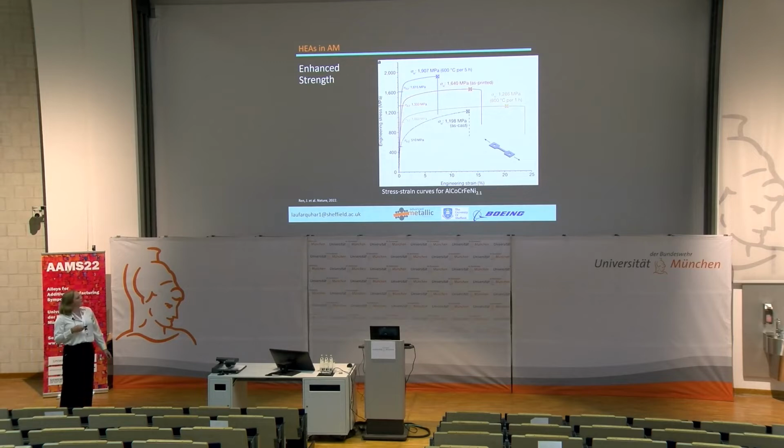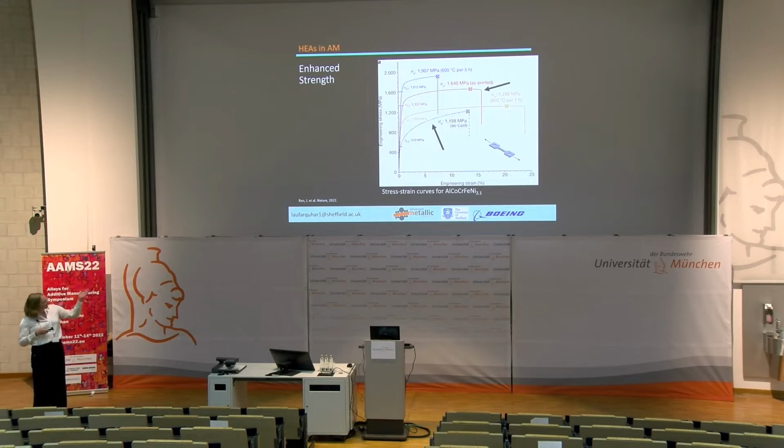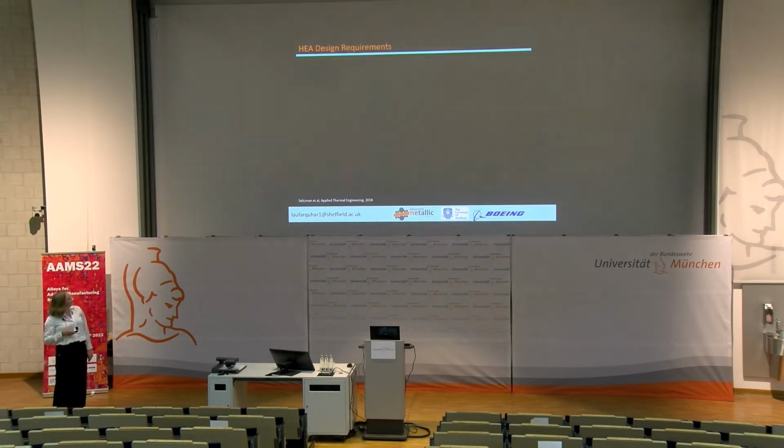They also, as with a lot of alloys, show increased strength when you manufacture them by AM versus casting, and that can be tailored by heat treatments as well. So this is as cast and as printed stress strain curves.